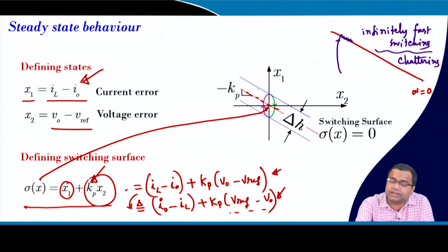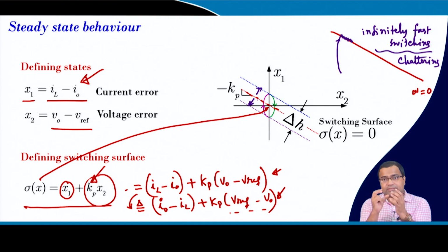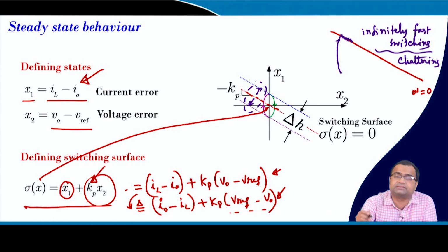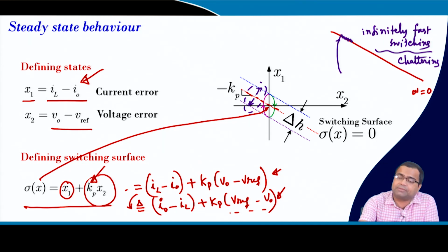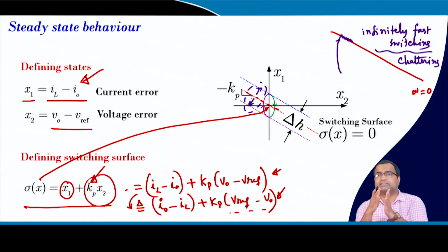That is why we need to incorporate a hysteresis band, which will introduce a dead time. That means, once you turn off, you provide some time and then it turns on again. This can be implemented either by a direct time based control, as we will discuss in a subsequent lecture, or it can be introduced directly on the trajectory by means of a variable, which is a hysteresis band.